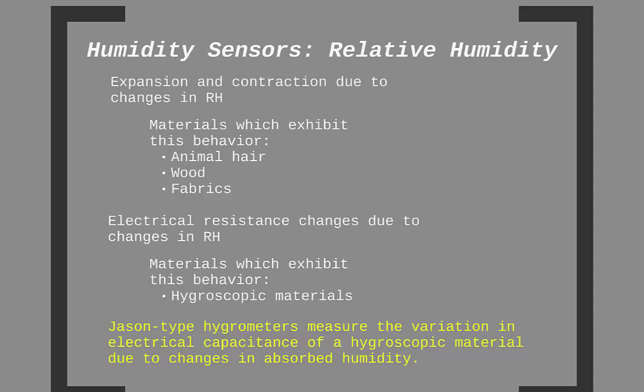As we said before, relative humidity is not the best measurement due to its dependence on air temperature. Thus, it is better to measure either humidity ratio or dew point temperature, both of which are absolute measurements of the quantity of moisture in the air.